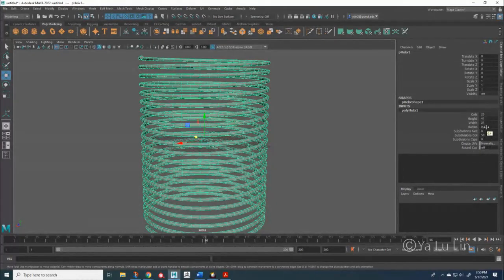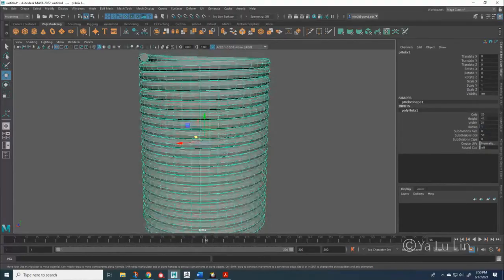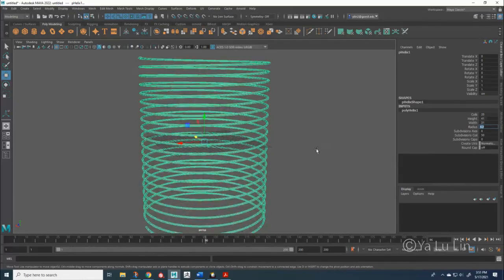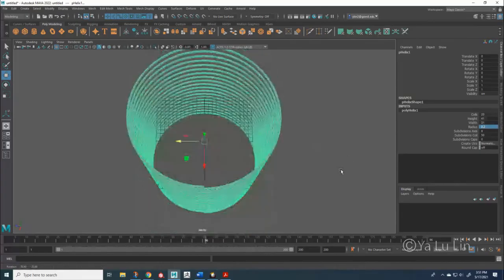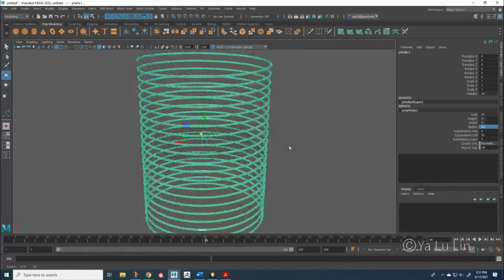You can change the radius here. So right now it's pretty thick or thinner. That's pretty thin. You can type in a value if you're not happy with it. So maybe I'll change to 0.02. Oh, that's too small. Maybe 0.2. There we go.